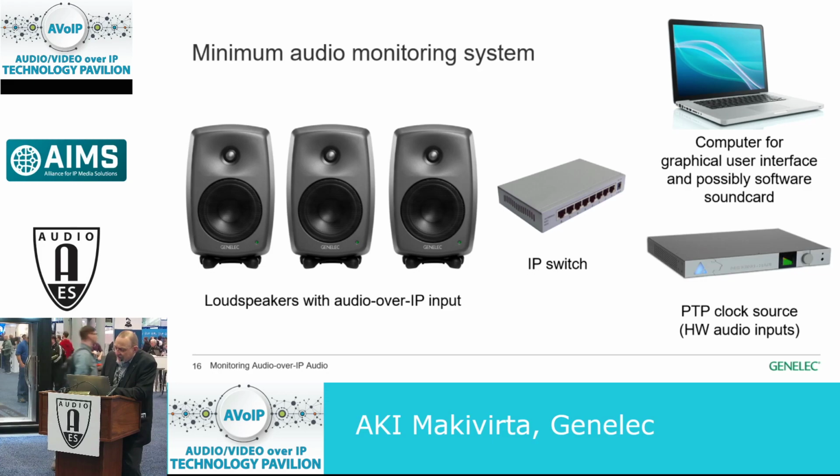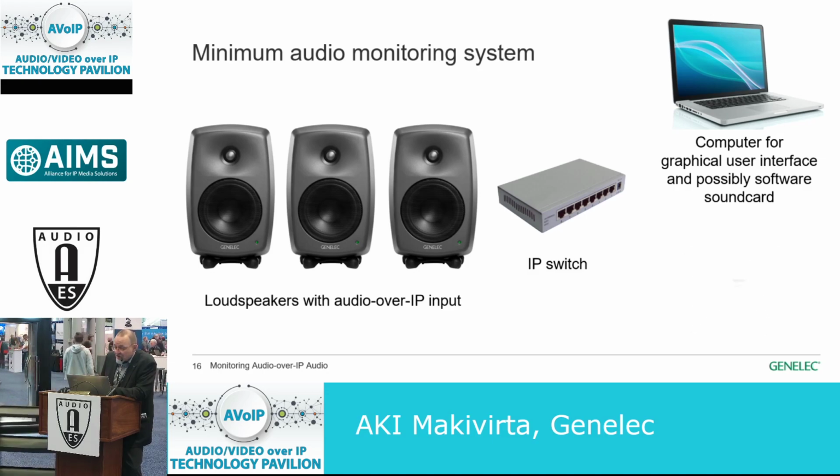On top of this, you usually need a Clockmaster device on the network. And this is very important because, and I'll come back to this in a moment, this device makes sure that all the devices on the network understand the absolute time exactly in the same way. Luckily today, increasingly, the devices that are able to deal with audio over IP streams are also able to act as PTP Clockmasters, and this means that most of the time your minimum configuration doesn't actually need this PTP Clockmaster device. That, what you see on the display at the moment, is actually your lightest possible audio over IP monitoring system.